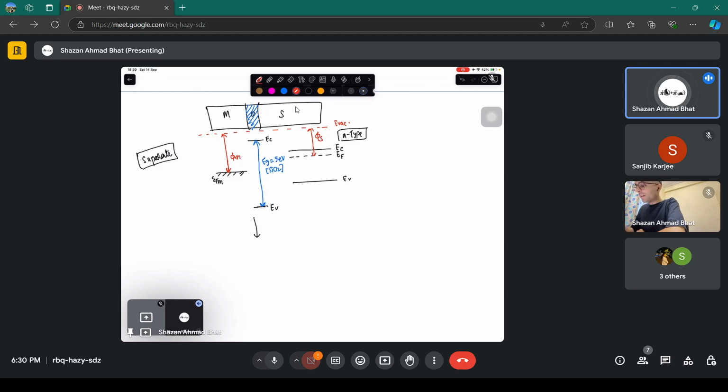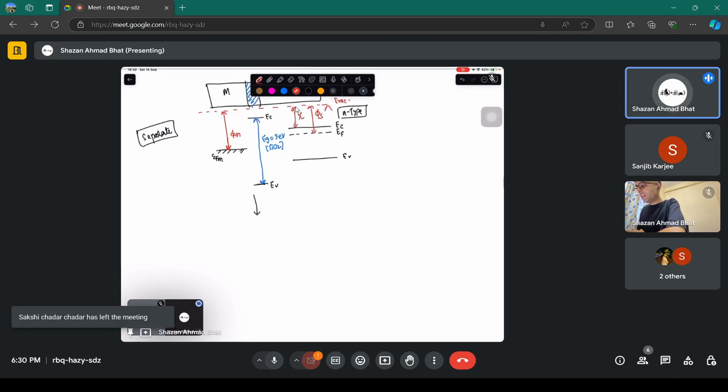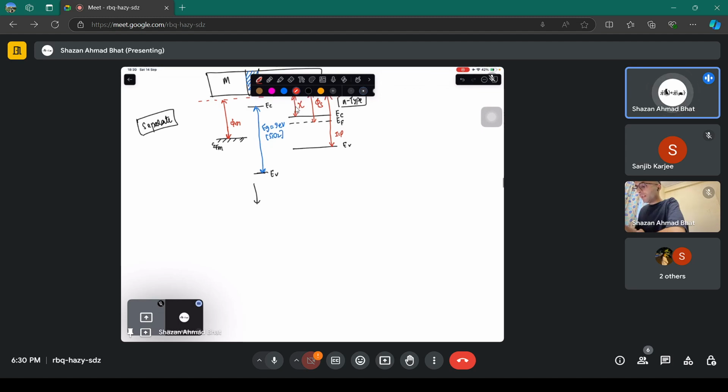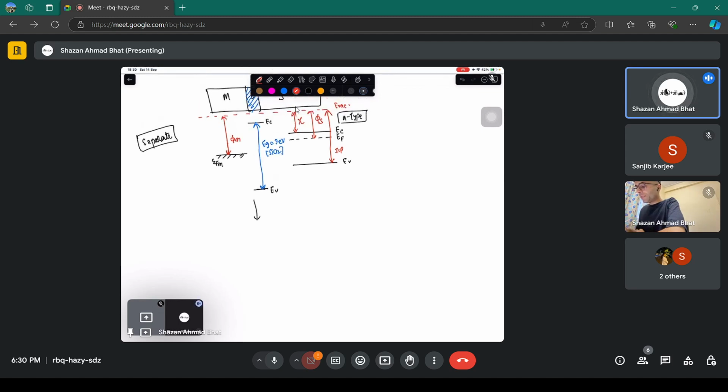the work function of a semiconductor, where the difference between the vacuum and conduction band is called electron affinity. The difference between the vacuum and the valence band is called ionization potential. We don't mainly deal with it because it takes huge energy to directly excite the electrons from valence to the vacuum level. This is the job of the high energy particle physics people. So let's not go into that. So what happens when you combine it?